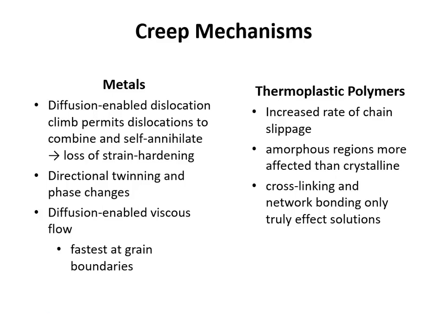And again, cross-linking can be strong or hard, very strong, full covalent cross-links like sulfur vulcanization, or we can go with very strong secondary bonds like thermoplastic elastomers. The stronger the cross-link bond, the more resistant you will be to creep, especially as you get to very high temperatures approaching Tg. Not, of course, that you should be using a thermoplastic anywhere close to Tg.